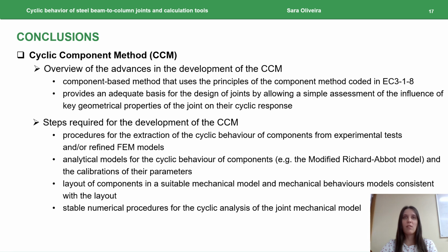The results gathered so far allow not only a deeper insight into the cyclic behavior of steel beam-to-column joints, but also have already proven that the cyclic component method provides a reasonable simulation of the joint behavior for the cyclic analysis and embodies a clear and powerful tool.